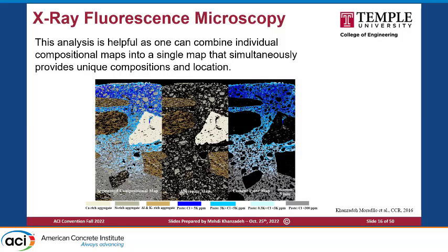You get the profile from this, and we already compared it with titration. There's a good correlation, so it's very useful for looking at chloride penetration. But the main point is that we can see the impact of different features: how an aggregate impacts your penetration, the distribution of cracks, aggregates, and so on.